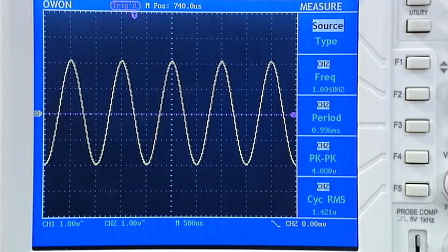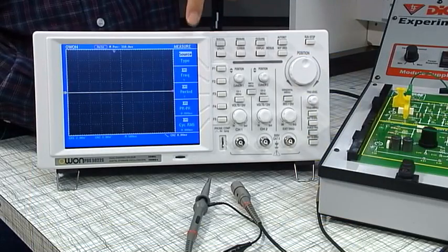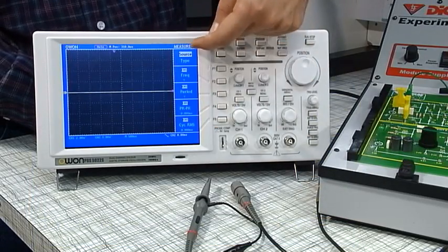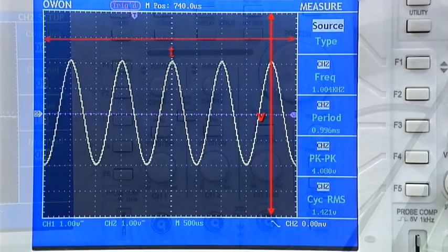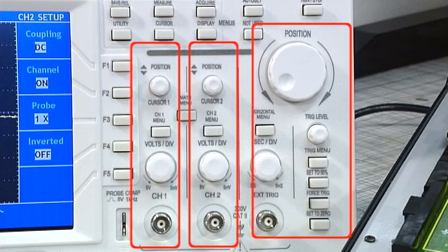The screen of an oscilloscope is used to display the voltage being measured. On the screen is a grid arrangement that can be used to take readings. Time is measured over the horizontal axis, while voltage is measured vertically. The grid is typically 10 by 8 divisions. The quantity that each division represents can be set using the time-base and Y amplifier controls.